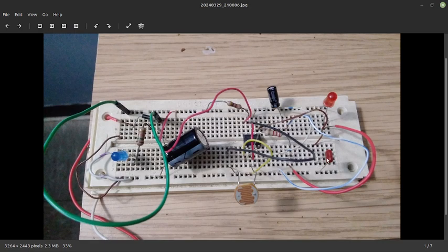This is the 0.01 from pin 5, control, which is here, the brown wire, pin 5, going to a 0.01. Actually it's 0.1 µF, but you could use 0.01 to ground. That's so that it doesn't cause extraneous behavior, because this is a CMOS chip, a high impedance chip.